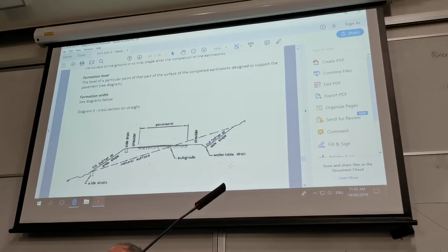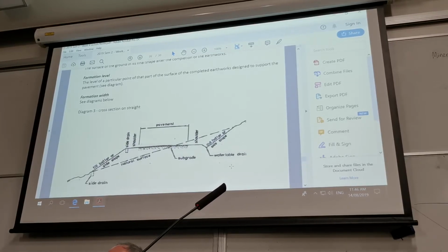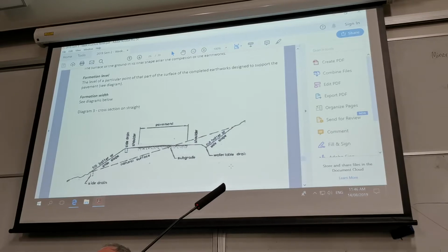And also for emergency vehicles, etc. So when you're designing a road, you work backwards from the shoulder, because you need the same strength all the way to the edge of the shoulder, which basically is the edge of the cutting for a platform or for a road. Therefore the geotechnical engineer has all the rights to go right to the edge with this design before he comes up with a ballast slope design.